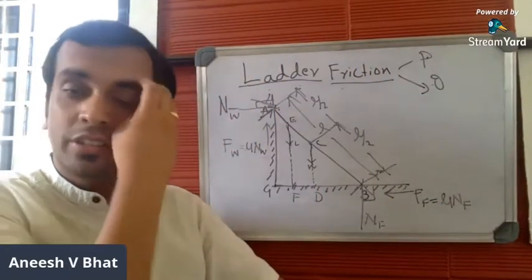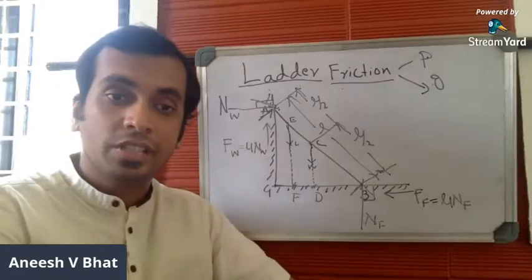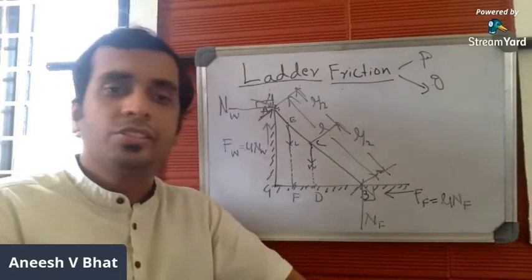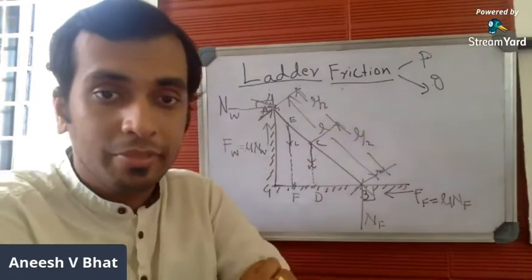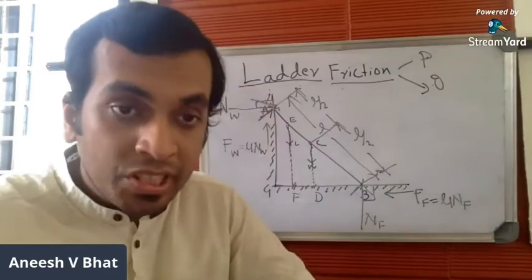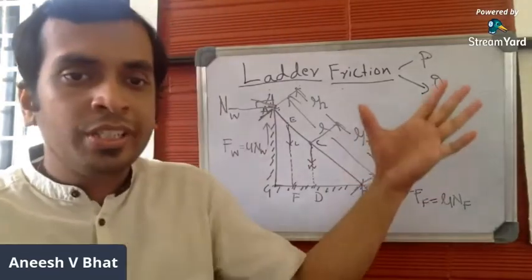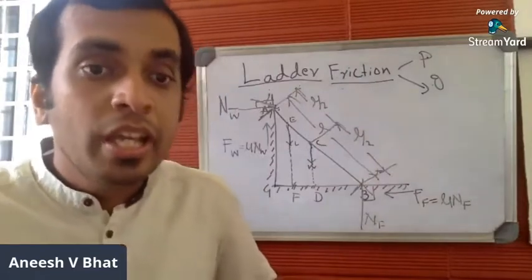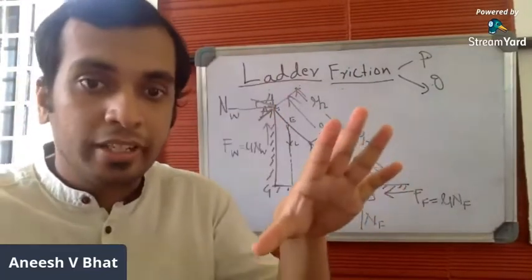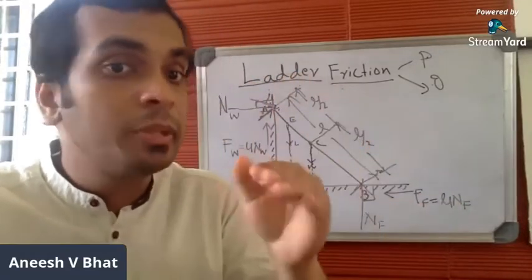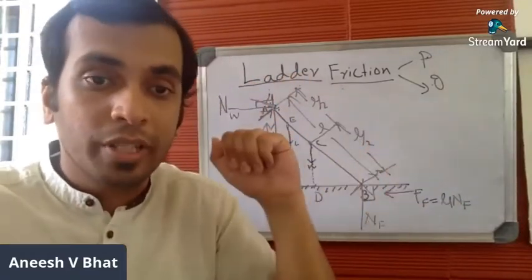So you mark the friction resistance as well. This is step number 3. After marking the friction resistance, you will not be drawing the free body diagram here. A free body diagram is a diagram where you bring all the forces to the center and make it a concurrent force system, and then you apply the conditions of equilibrium. If you draw the free body diagram, then it's enough if you apply only 2 conditions of equilibrium, as we went through in the previous set of numericals.